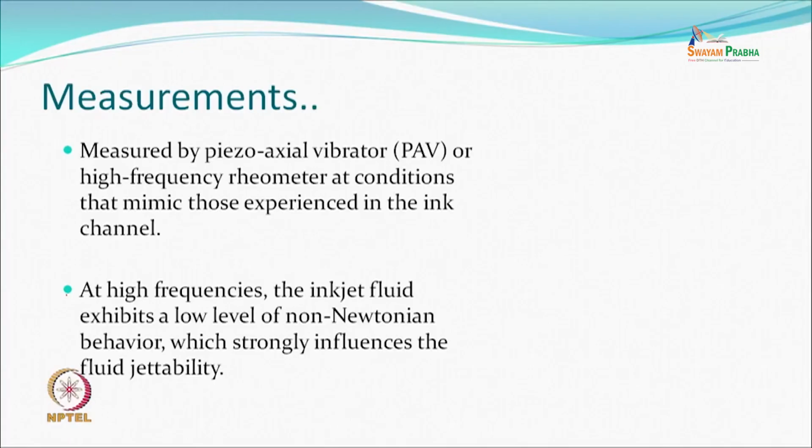For example, a high frequency rheometer, a condition which can be mimicked by these rheometers, which are approximately the same type of condition which the ink experiences in the channel. At high frequency, the inkjet fluid exhibits a low level of non-Newtonian behavior, which also strongly influences the fluid jettability.